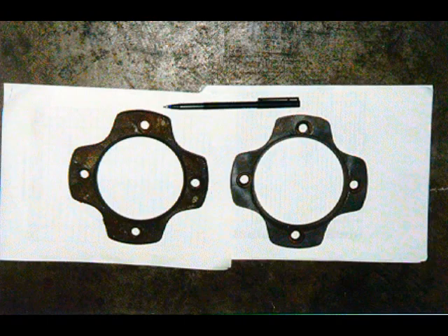During operation of the plunger pump, be on the lookout for a number of conditions or problems. First is excessive wear of the plunger. Check the amount of wear on the plunger whenever the packing is changed. Refer to manufacturer's literature for allowable wear. The housing that holds the ball check valve and valve seat can also become worn with use. If the valve seat is worn, there will not be a good seal between the seat and the ball. The condition of the seat should be checked periodically and changed when necessary.